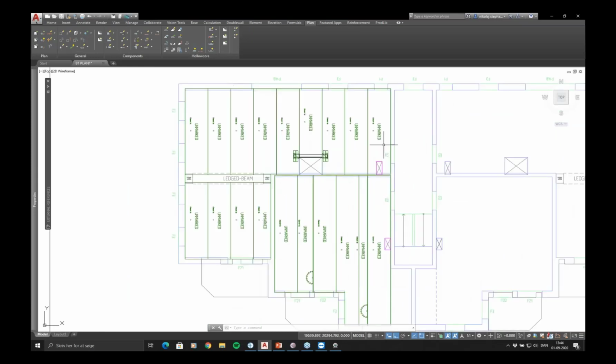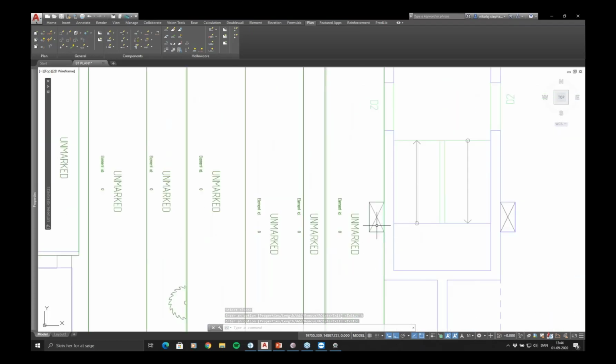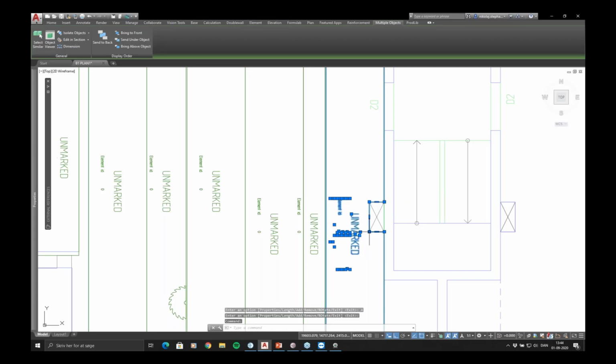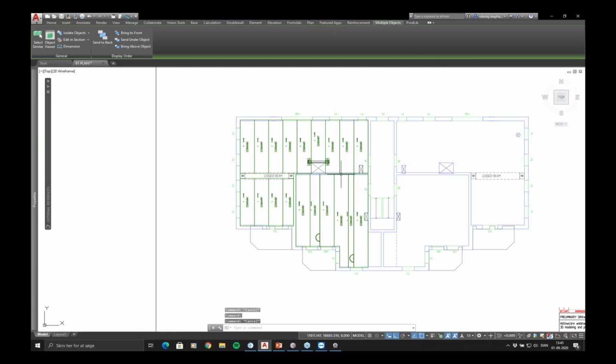So for these, where you can see these purple boxes here, I want to actually have them subtract. Right now they're just put in as purple boxes, so I can move them around, I can copy them, I can do whatever I want with them. But what I want to do now is actually add them into these slabs. So we'll first add here. And what you can see now is the outline of the slab will actually follow here. So this is a cut through. The same thing with this one here is also cut through.